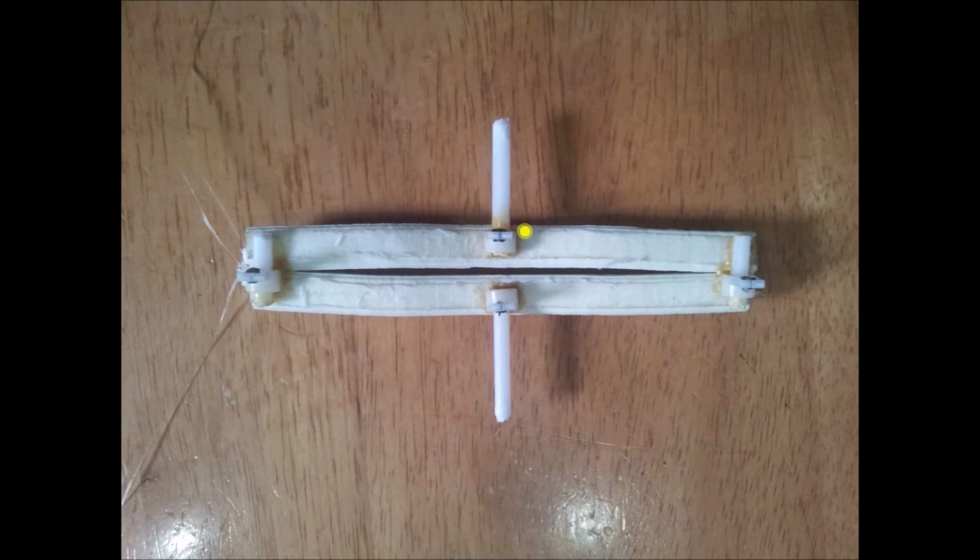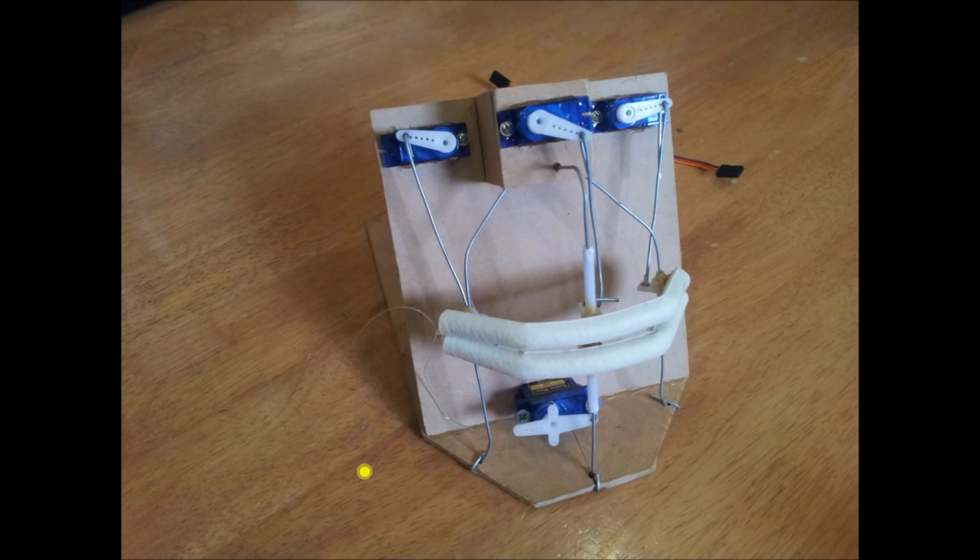We've got the control rods with the central lollipop shafts that fit over the 1.25mm wire and allow the movement of the lips up and down at the corners and at the centres. You can still see the necklace string, which is slightly elastic. Inside each of the lips there are 3 sections of lollipop stick which allow it to just form a nice lip-like curve. Here we see the final mouth mechanism, a frame of MDF which supports 1.25mm wire which provides guides